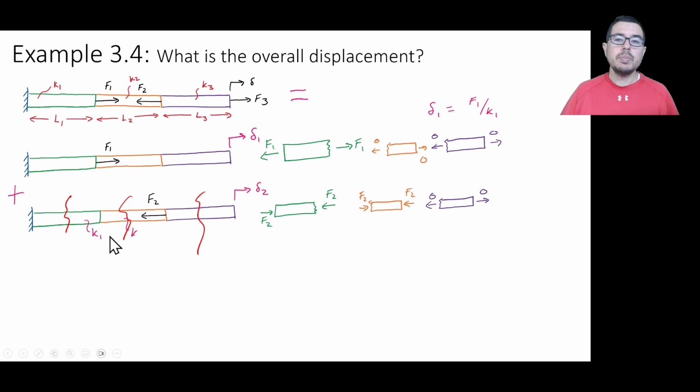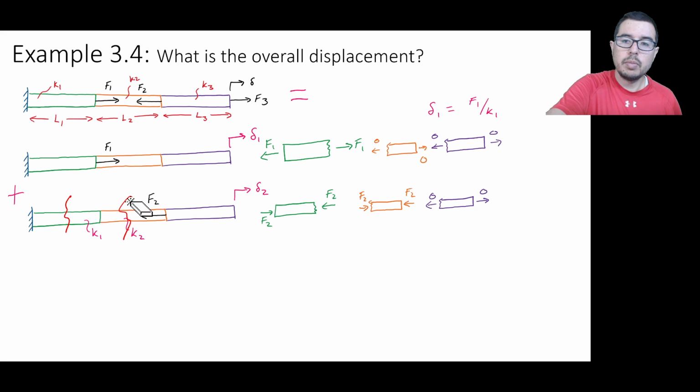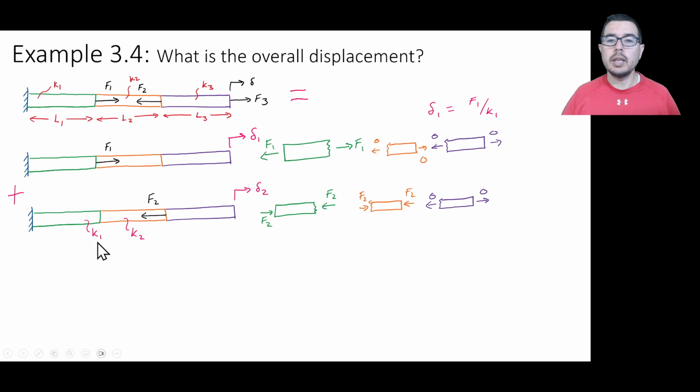And we have spring constants associated with the middle and the left region, and those are K1 and K2. There may be a couple of different ways to look at this. One way, though, is to say that we're going to assign an effective spring constant for this region and this region, for the entire bar. We're going to think of it as, I'm applying an F2 that's going to be putting these two regions under compression. So K effective, these are springs acting in series, is going to be K1 K2 over the quantity K1 plus K2.